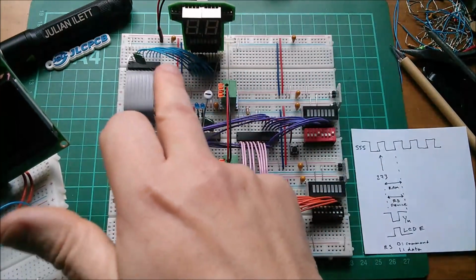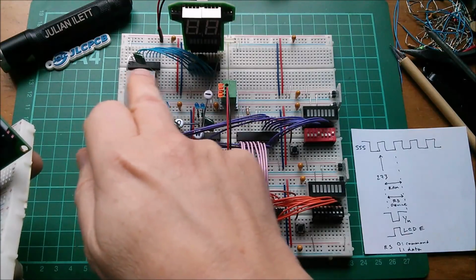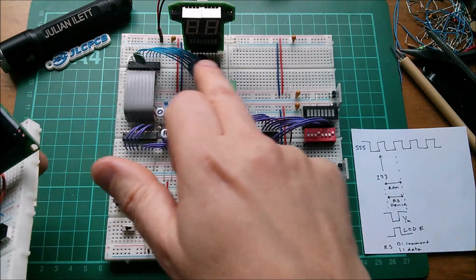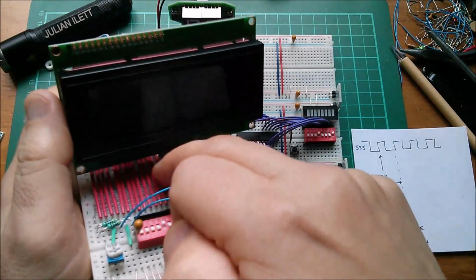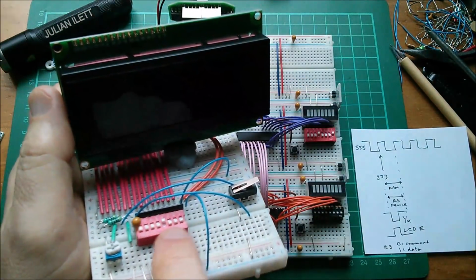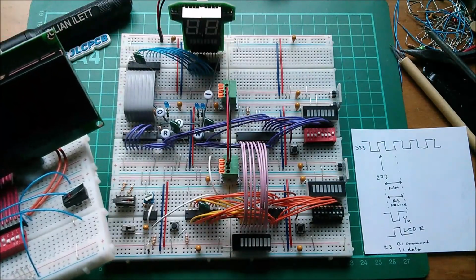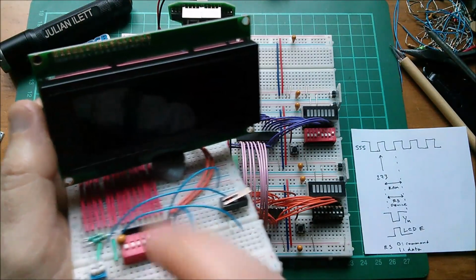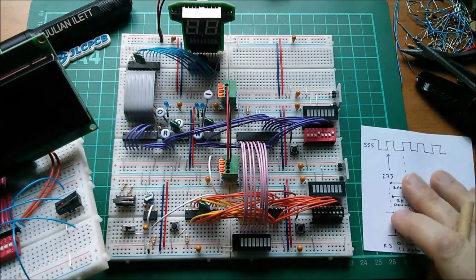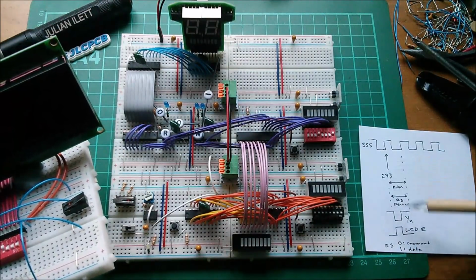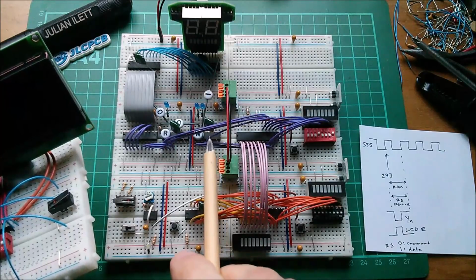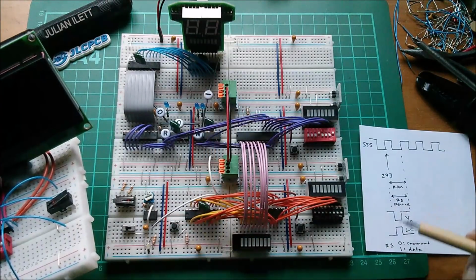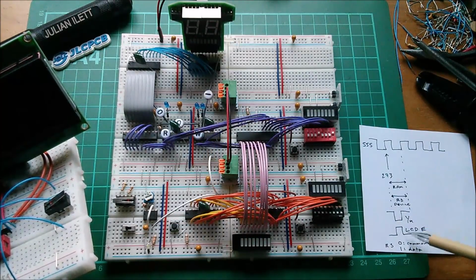At the moment, the data bus can only read one readable device and write to one writable device, but I can extend that on so that it sits on the 8 data lines of this, which is where this switch is. The enable line on here, I've determined, according to this, that I need to invert one of my address decoder outputs because enable needs to be a positive going pulse.